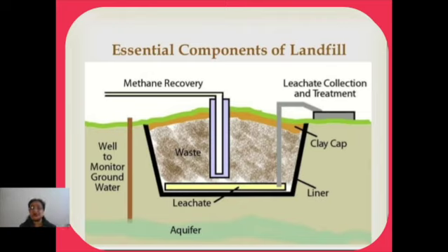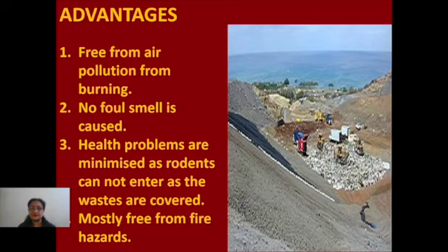Moreover, all the waste is dumped and covered. After that a thin layer of soil is spread over it. So that, to some extent, is not going to cause the pollution which was seen in the case of open dumping. The several insects and rodents and all which were seen in the case of open dumping are not seen in this case in the sanitary landfills, right?